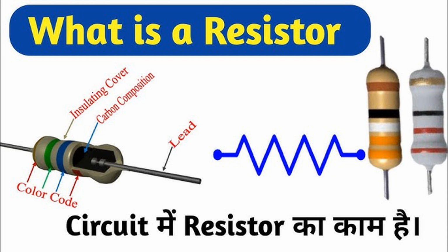Understanding pull-up resistors. Purpose: A pull-up resistor ensures that a digital input pin reads a high, logic 1, state when no other component is driving the input. Without a pull-up resistor, the input might float, leading to undefined or fluctuating logic levels, which can cause erratic behavior in digital circuits.